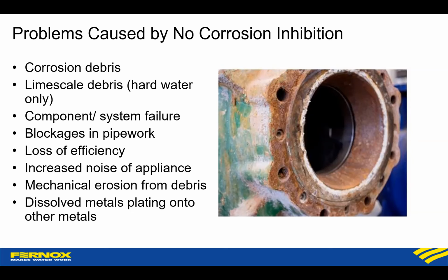If you get a bit of limescale in the pump, or there's some sludge, maybe there's an ERP pump involved which has a magnet in it, and so it's collecting a load of magnetic iron oxide, that's going to cause a grinding sound, and as well as eventually causing component failure, that's going to cause issues with noise as well.